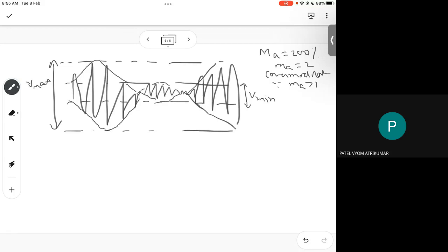If you see here, another band has come here. This is what we call splattering, which we have seen, where one channel will go into the next channel. So this is the experiment that you will be doing for various modulation indexes and so on.